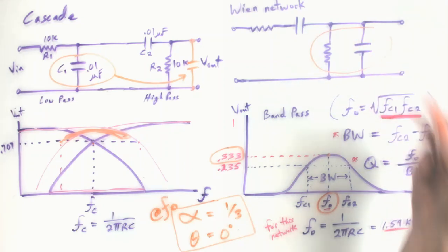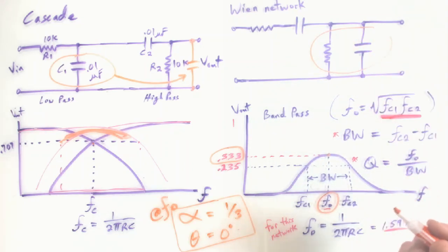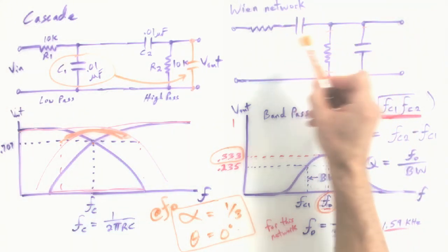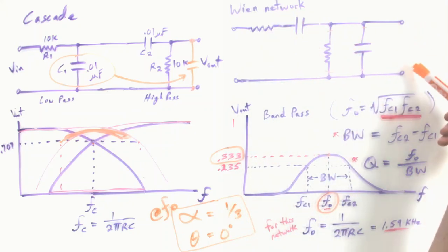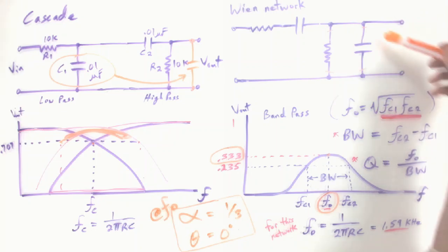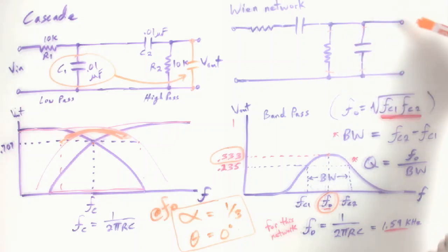So you're going to have sort of that thing going on. So yeah, low frequencies, this gets all the voltage drop, and there's nothing for the output. And at high frequencies, you've pretty much shorted your output. This looks like a short, and you get 0 volts across your output for that reason.